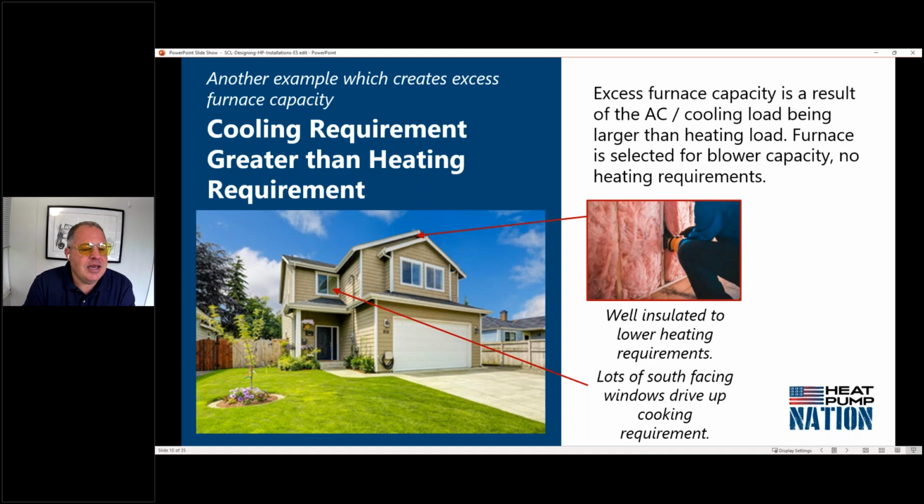And it's a little complicated, but the airflow characteristic or specification, they're linked to each other between the outdoor unit's requirements and that furnace's capabilities. And so, for example, in the Portland metro area where I live, I often had to sell 100,000 BTU furnaces because it could move enough air for the 36,000 BTU air conditioner I needed to install. And so that heating load of that house might only be 30,000 BTUs, but I had to install a 100,000 BTU furnace. It's really unfortunate, but there was really no way around it.